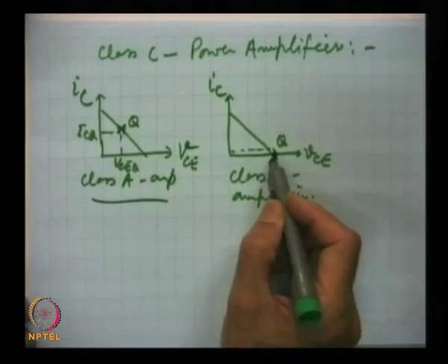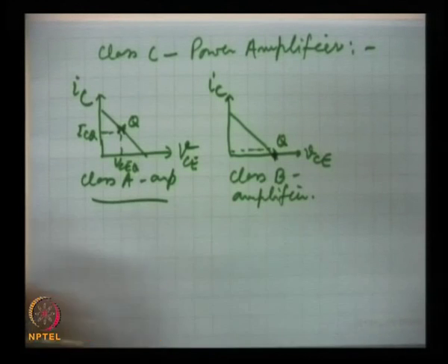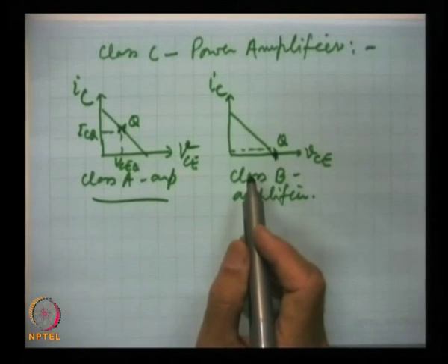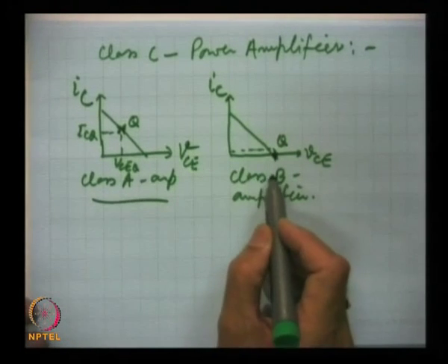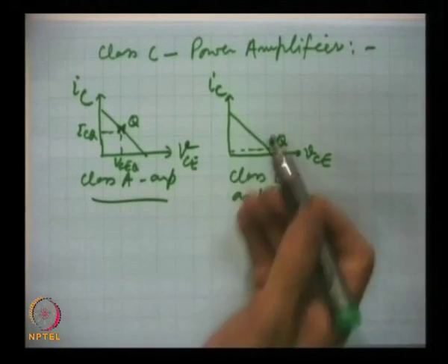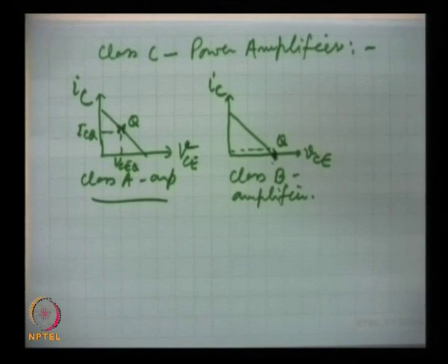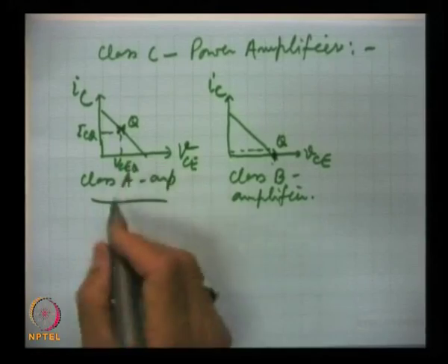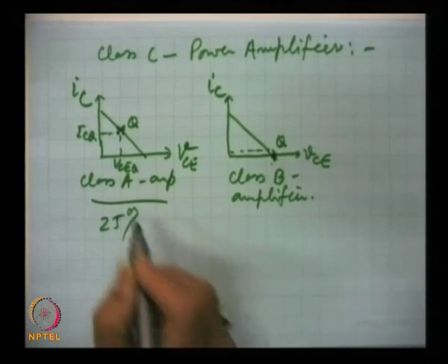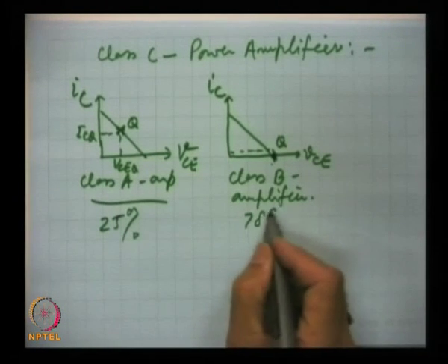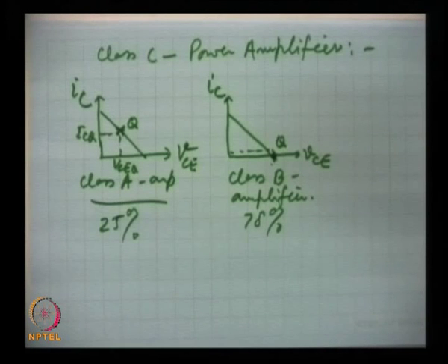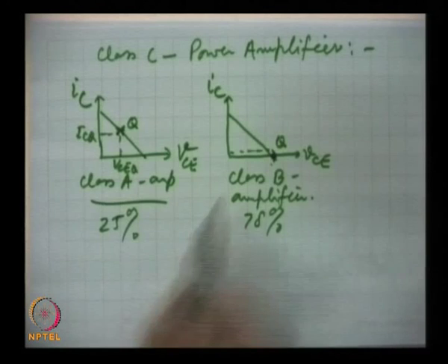When the input signal comes, the transistors will be conducting, and then the whole process starts. The efficiency here is 78.5% theoretical, but practically the efficiency is close to 70% in well designed circuits. Now, this was the cutoff point.